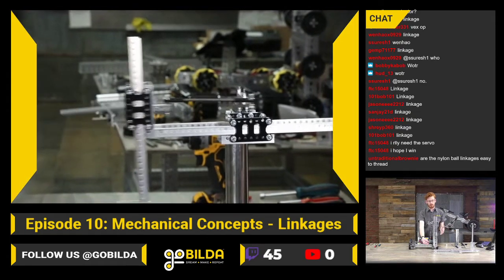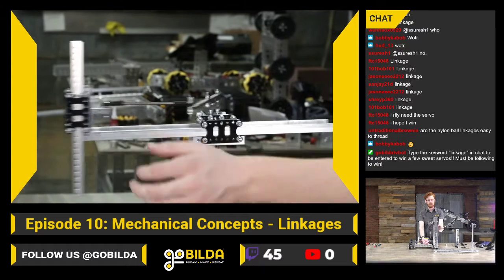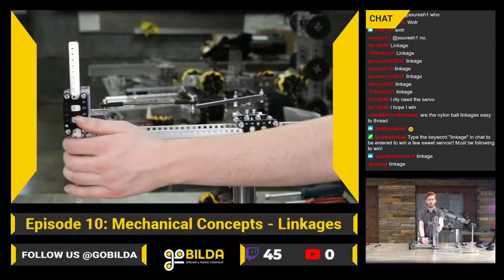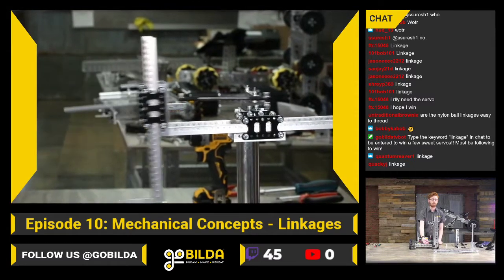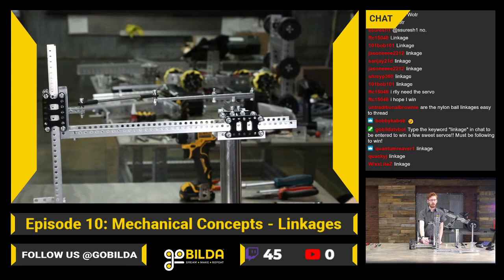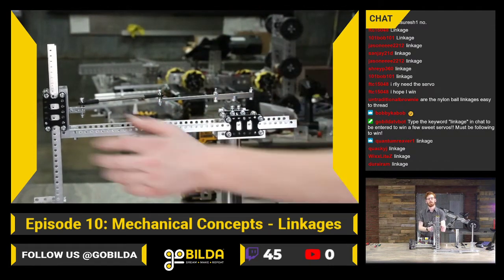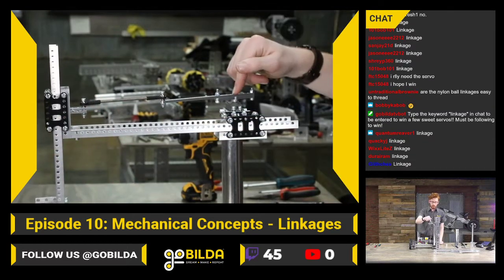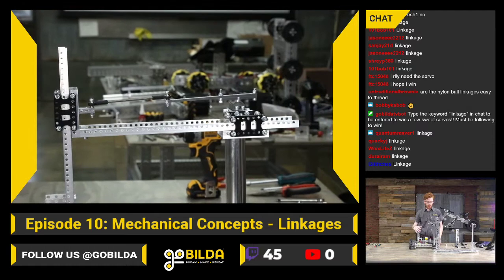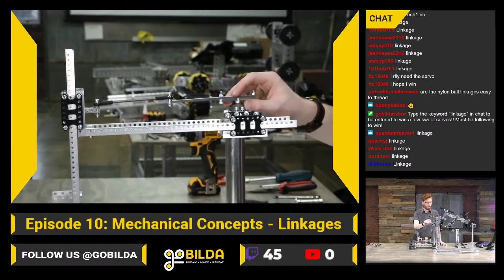That means this fastest part of the linkage will also be the point of linkage where the servo has the least amount of force. And when you hit the ends out here, this is where you'll have the most amount of force. And this can be really nice. If you're designing a claw that has a linkage, if you design it so that these bars end up parallel, you can push on this as hard as you want, and until you snap the spline off your servo, you're not going to backdrive that servo. And that coincidentally means that servo doesn't have to work very hard at all to hold that position.